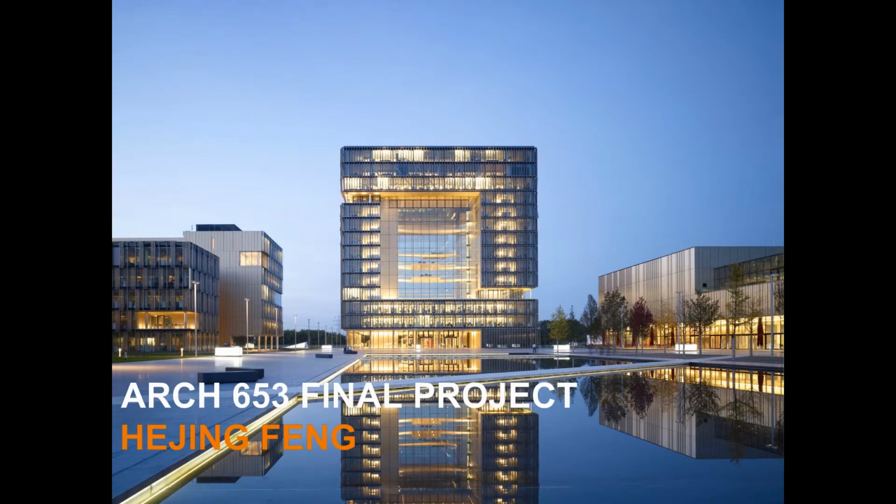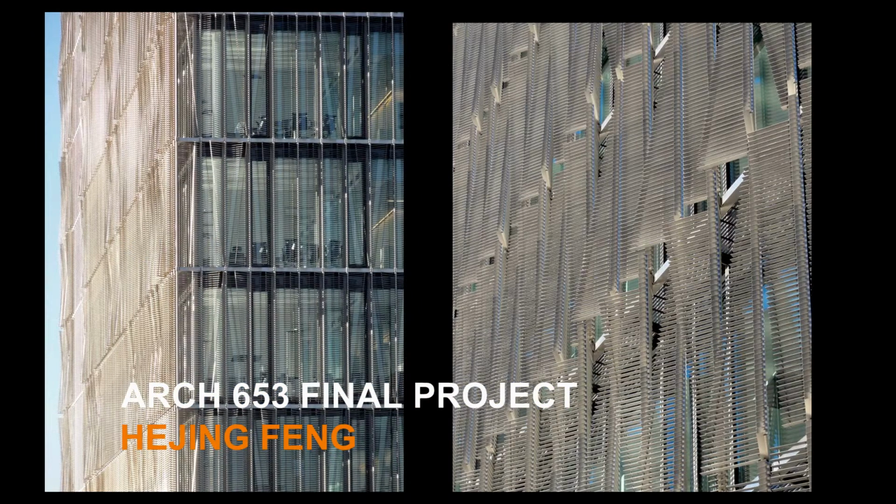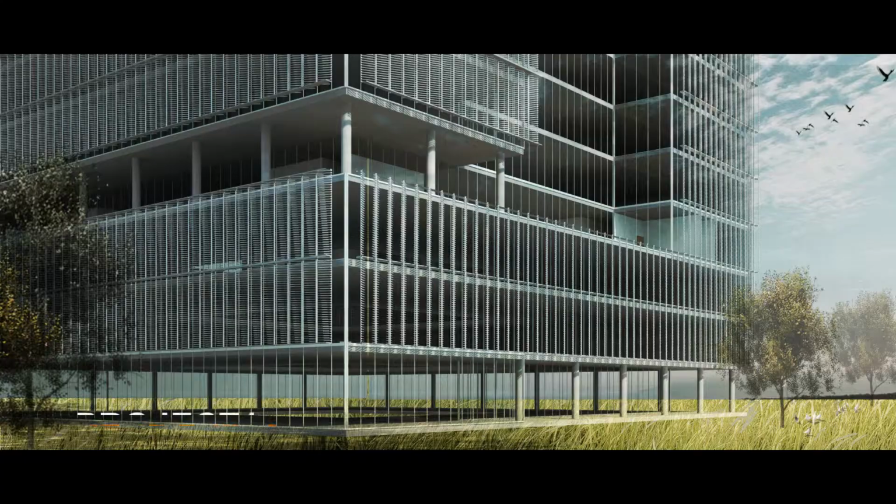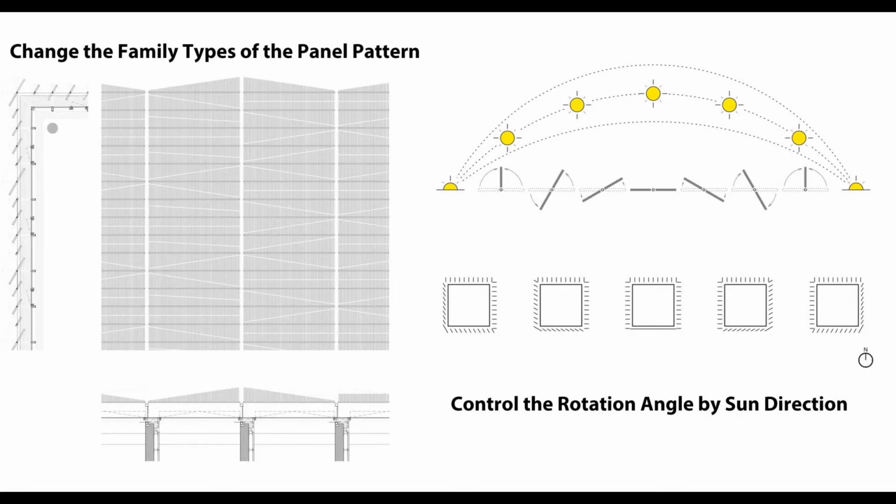My final project will continue working on the building facade of Q1 Sassoncraft Quarter Essen. I was not able to dig into details for the curtain panels in Project 1, so this time I'm going to look at two issues: to change the family type of the panel patterns and to control the rotation angles of the blades by the sun direction.